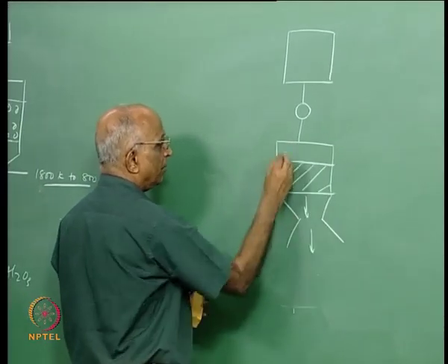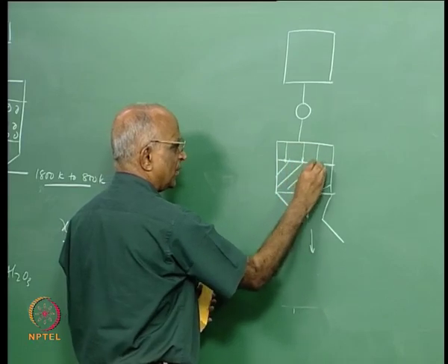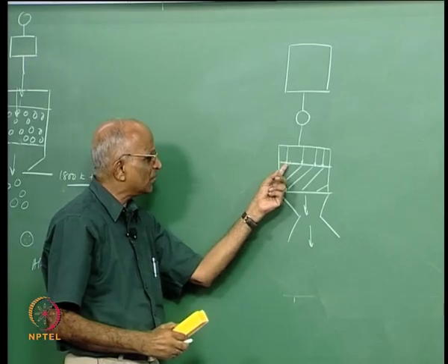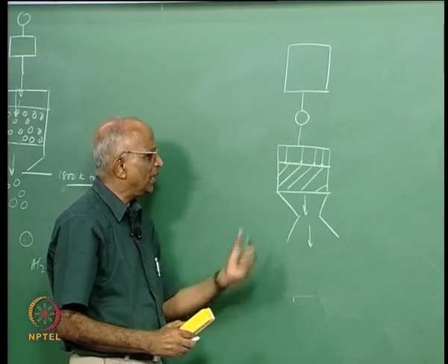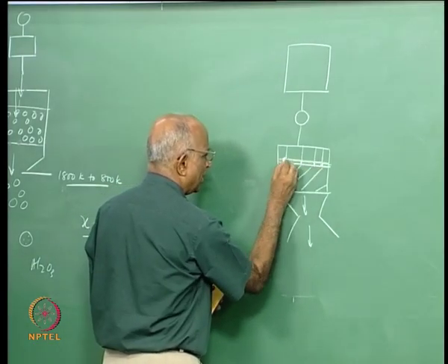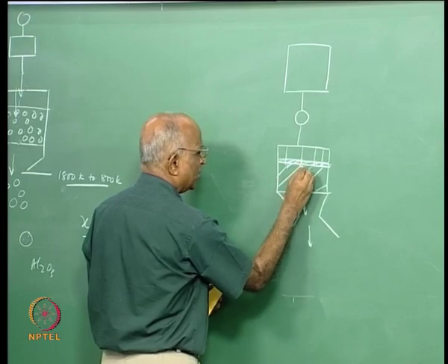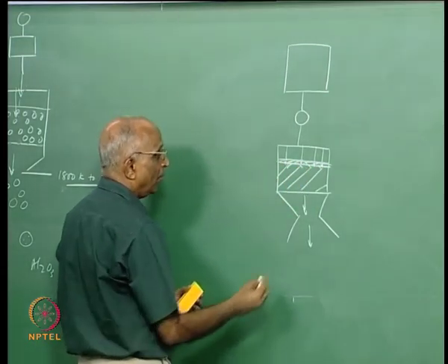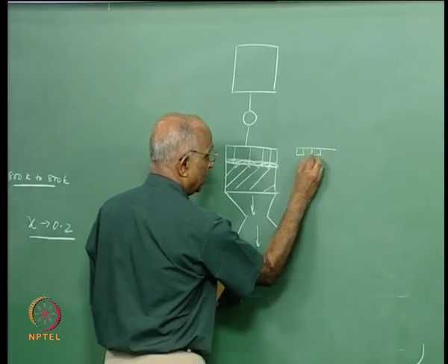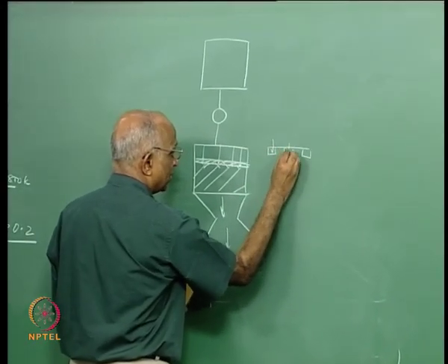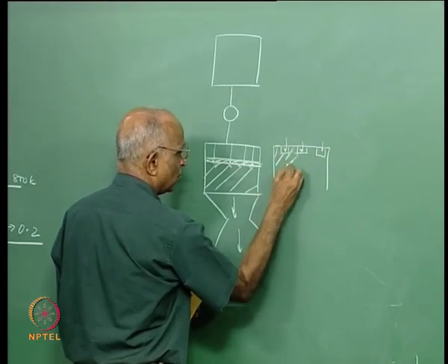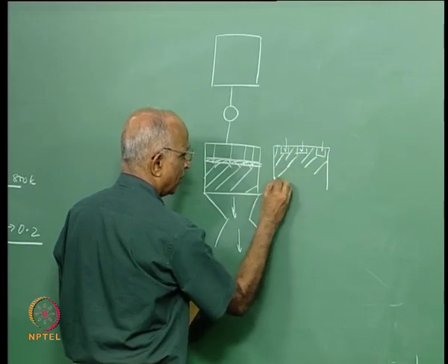I need an injector, maybe an ordinary shower head injector which forces the liquid on this is okay, but if I force it like this on the bed, it does not get uniformly distributed. Therefore, maybe I could put some metal screens here, impinge it on the screen and distribute it uniformly, that is one solution. Or else I could allow the bed to be very near. I put metal screens over here, inject it as a shower head, and impregnate the catalyst bed right at the injector. This is one other configuration of doing it.